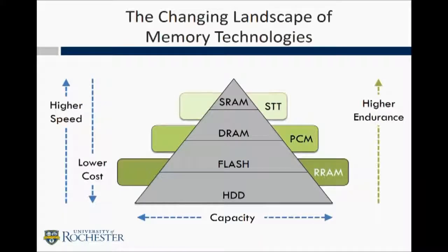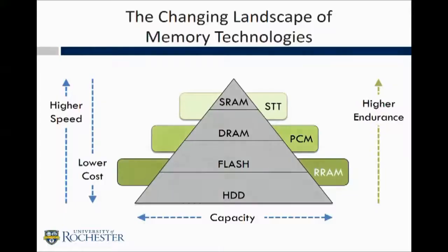With the emergence of resistive memory technologies such as STT-MRAM, phase change memory, and RRAM, the spectrum of devices that are now available to a computer architect to design memory systems has enormously increased over the last 10 years. These technologies are initially being pursued as replacements for today's SRAM, DRAM, and flash-based, charge-based memory systems. But beyond that, they also offer some unique capabilities to do computation in fundamentally different and new ways.